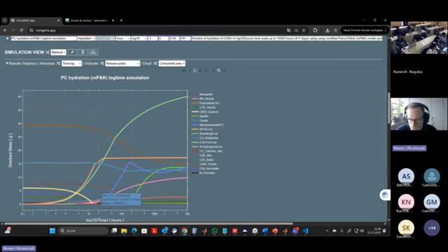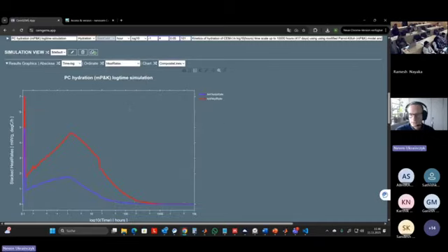Or, yeah, this one. So it goes up to, what is this? Like 2%, a very, very low percentage of portlandite. Because we have formation of strätlingite and other phases. Probably you will get more portlandite in realistic systems, I'm assuming. And then based on this amount, you can tune your reactivity for your pozzolans.